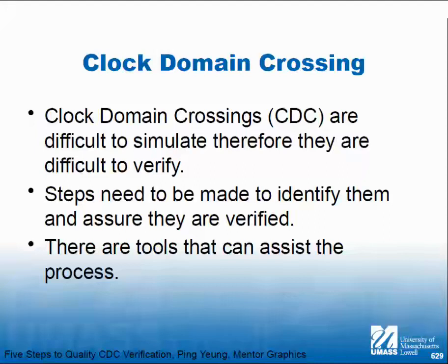And that is what's going to physically show up. So you can't rely on the simulator alone, the digital simulator, to verify your clock domain crossings, because the models are based on discrete numbers, and the problem, metastability, is based on continuous.